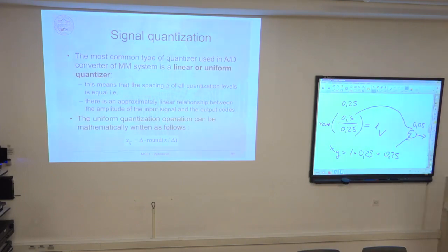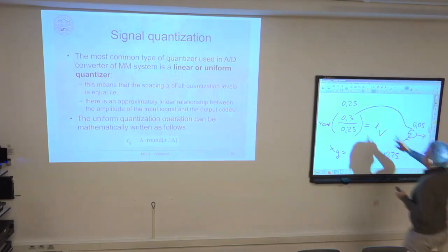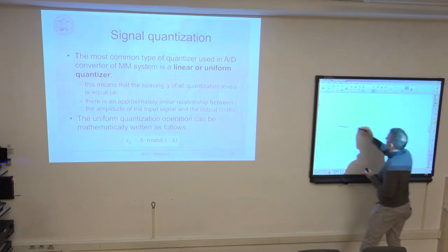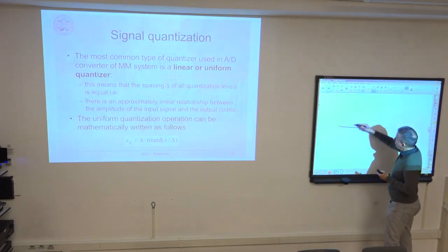And I know that this rounding creates an error that is always in the range of plus or minus 1/2 of the quantization step. Because if I'm slightly below the half above the level, then I have the maximum positive error. I have to plot it. So this is the midpoint value.